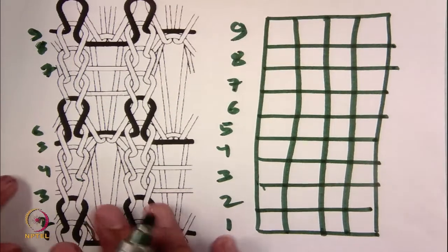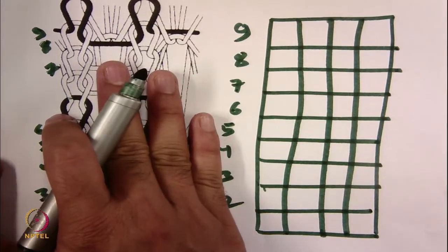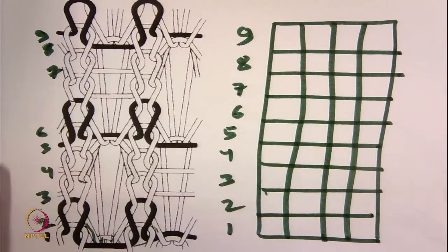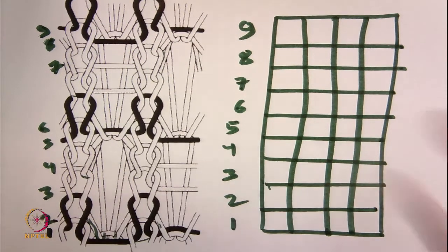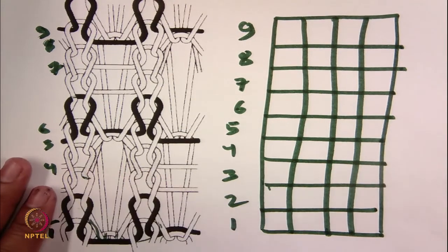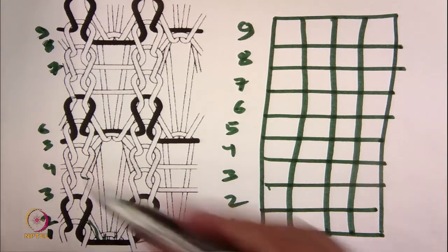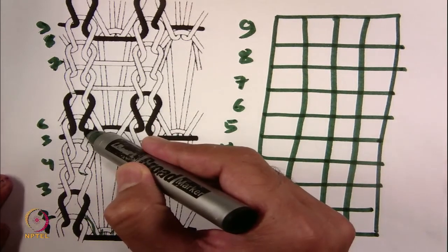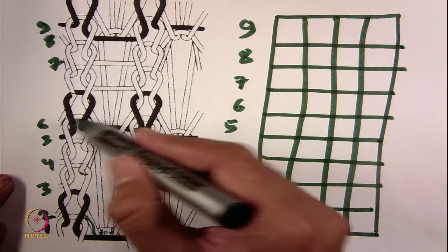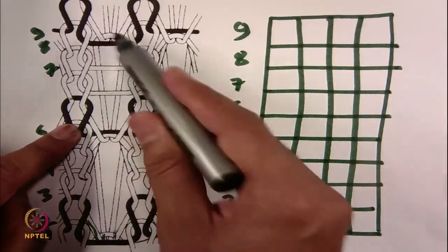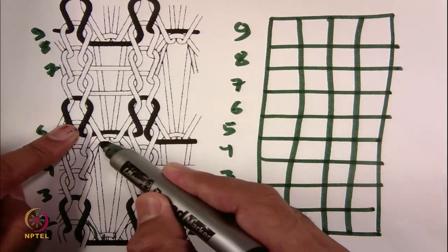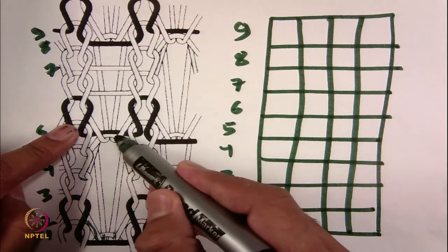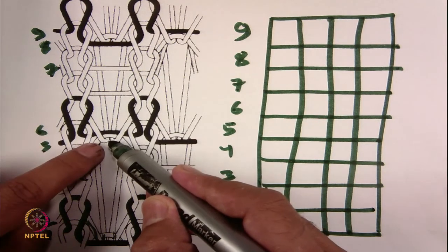Now, you also have to identify whether this fabric belongs to single jersey or double jersey. To find out whether a particular fabric is single jersey or double jersey, you have to see whether you can have any technical front as well as technical back loops on the surface. So, you have to identify technical front and back loops. If you see this black one, this is technical front because the legs are on the front side. Now, if you see this bigger held loop carefully, the legs are going behind. So, you can see the leg side of this particular loop is going behind. So, naturally this is the technical back side.